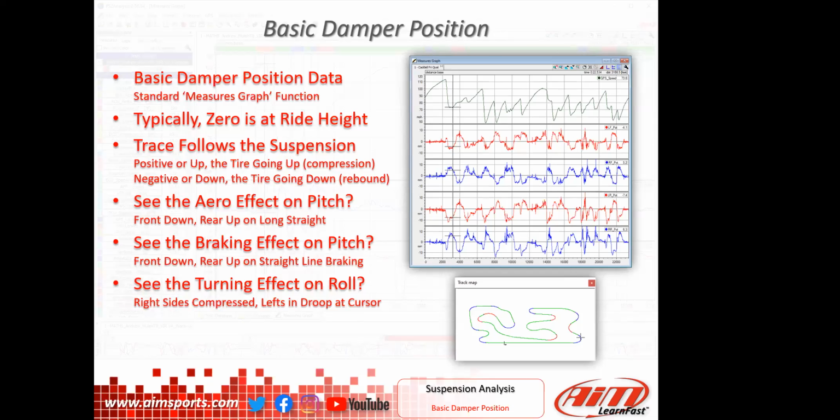Now, all of a sudden that rear end had been up, but now he's starting to add lateral Gs to it. And now that right rear tire is being packed up into the wheel well. So you can see the transition from being down to crossing over zero and then being packed up into the wheel well as the car is starting to transition from longitudinal Gs to lateral Gs. And you can see that the inside tire, the left rear, it went down and stayed down.